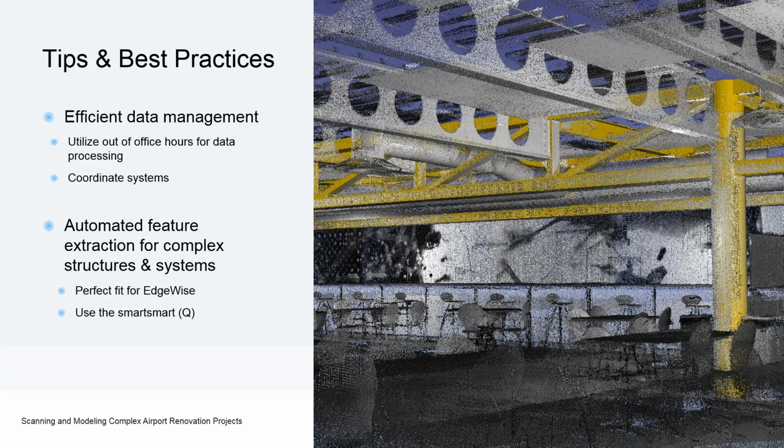And if you bring that into Revit, it's going to offset it to the origin, normally by center to center. I think it likes to do it, which isn't very useful. So we tend to sort out the coordinates to begin with a simple shift in northings and eastings so that it's nearer the origin, but leave the rotation, etc., as it is and the levels as they are. And then we can just sort out the shared coordinates at the end quite easily.